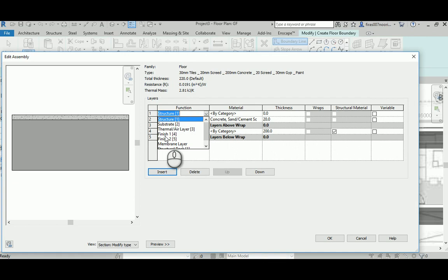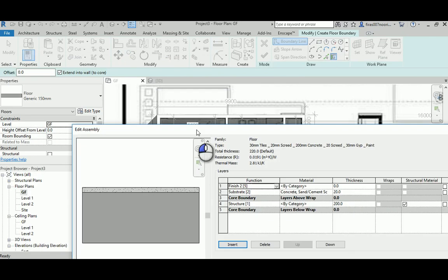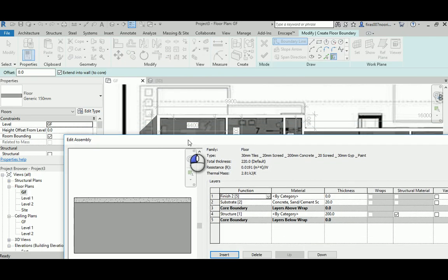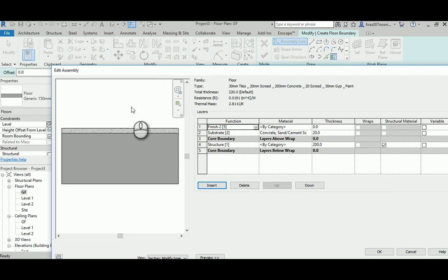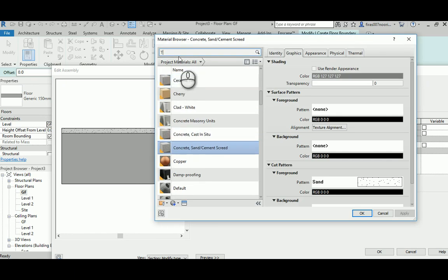That's the issue. Now I know that there is a slab or floor above me, so for now I'll assume it's finish 5 as interior on both sides, because I'll design this slab to be exactly on top of the ground floor. Above me will be the first floor, and beneath will be the ground floor. So that's what I'm doing now. Here finish 5 and here finish 5, interior on both sides. Here I need something with tiles, so any internal tiles.